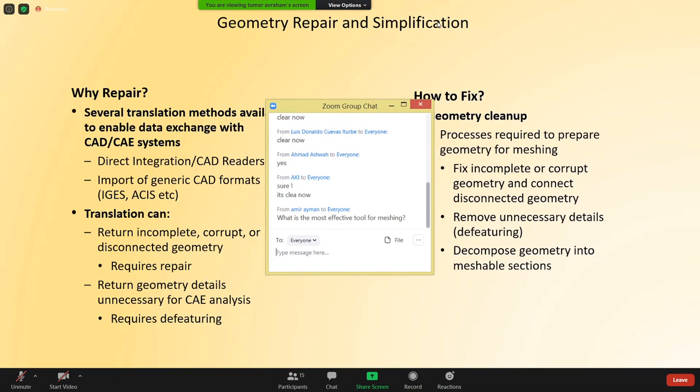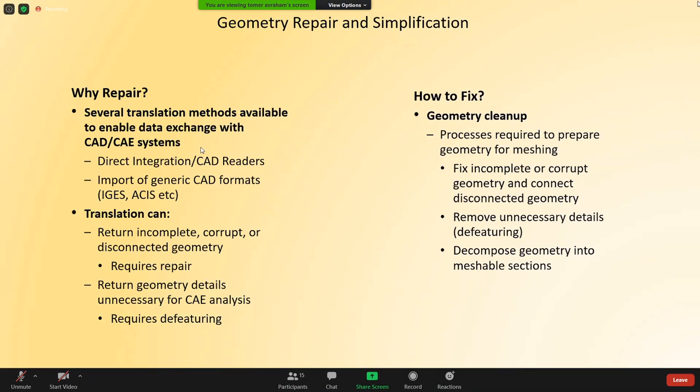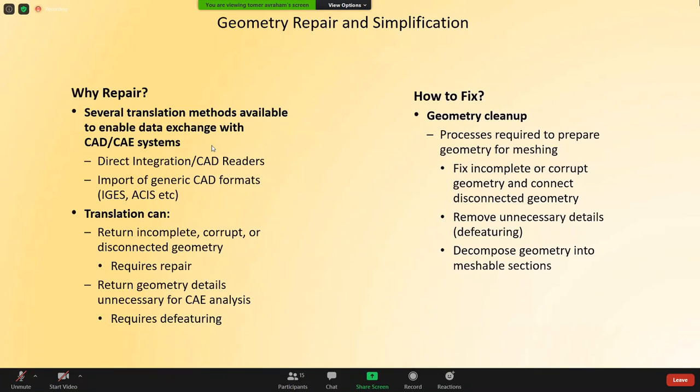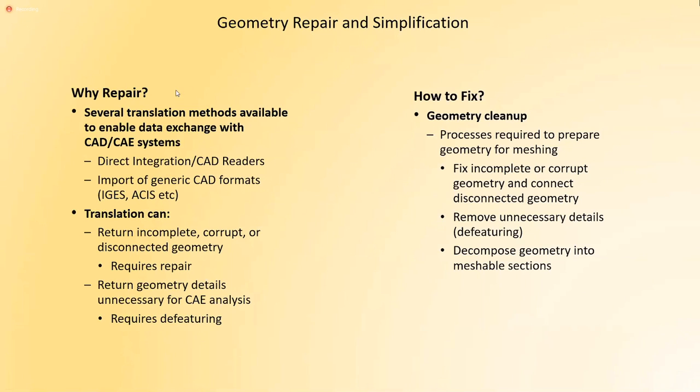Okay, thanks. What I said is never take. Usually, you can read with Fluent or other platforms directly SpaceClaim, SolidWorks files or others. Don't do that. It's very problematic.